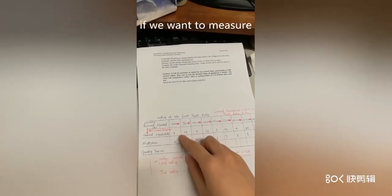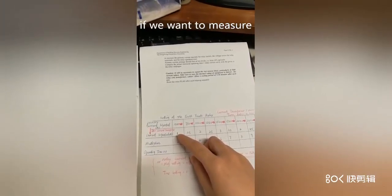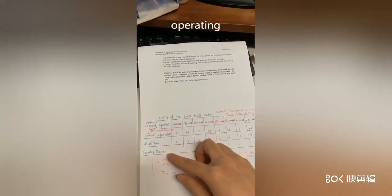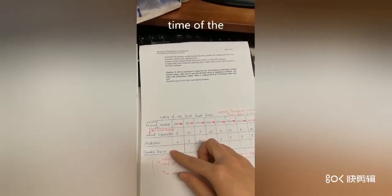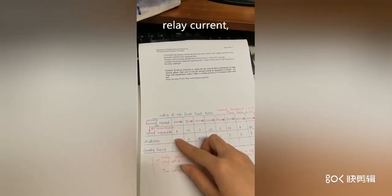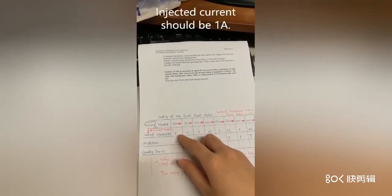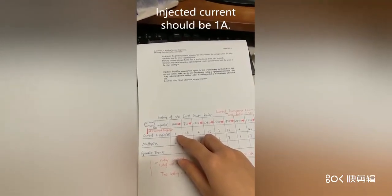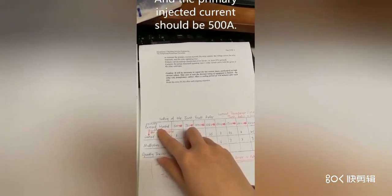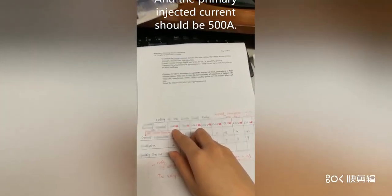For example, if we want to measure the operating time at 2 times the relay current, the injected current should be 1 ampere, and the primary injected current should be 500 amperes.